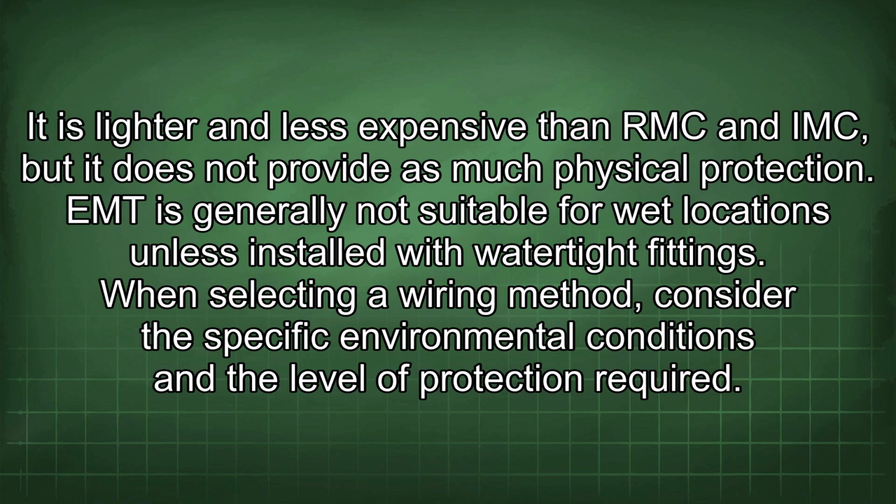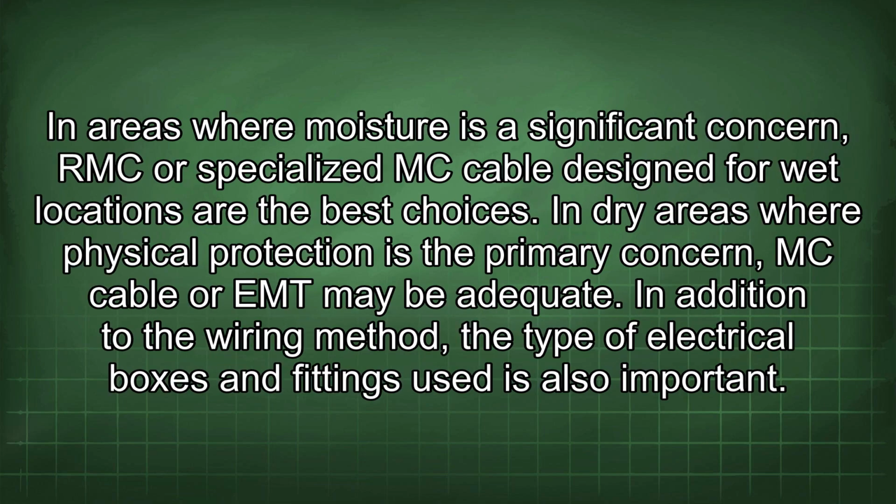When selecting a wiring method, consider the specific environmental conditions and the level of protection required. In areas where moisture is a significant concern, RMC or specialized MC cable designed for wet locations are the best choices. In dry areas where physical protection is the primary concern, MC cable or EMT may be adequate.